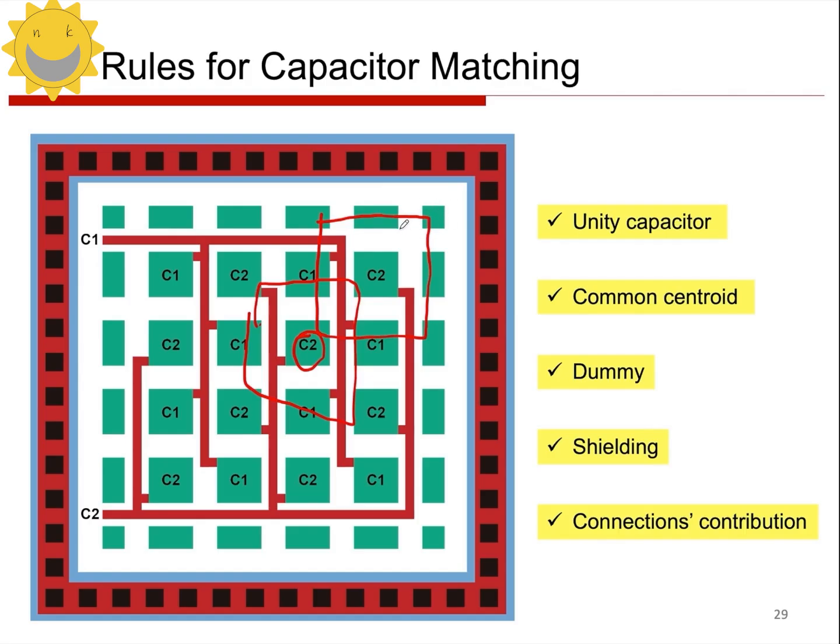It might seem like they are wrapped with dummy, but be careful. In reality, the shape at the corners is different from the inside. You can see that the corners inside are not connected. They are empty, and they are not connected. The dummy at the edges should not be connected either. In this case, the dummy at the edges should be a very small segment, not a rectangle. Note that this is for dummy devices.